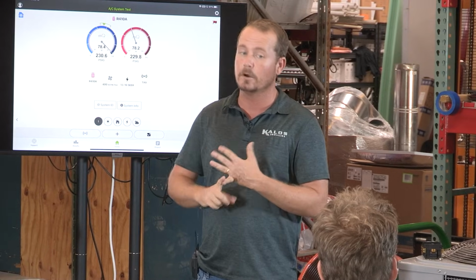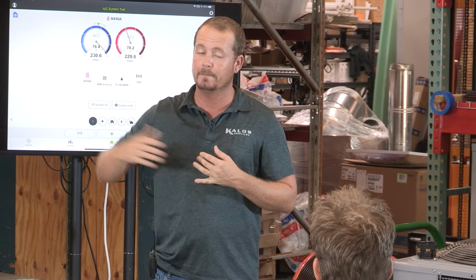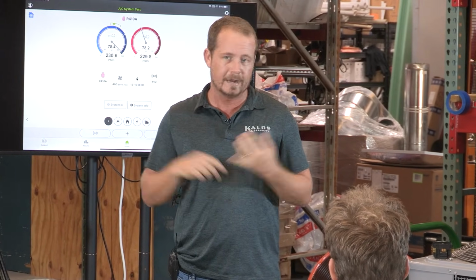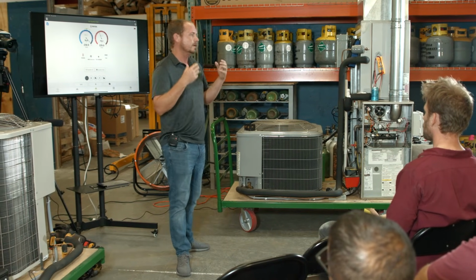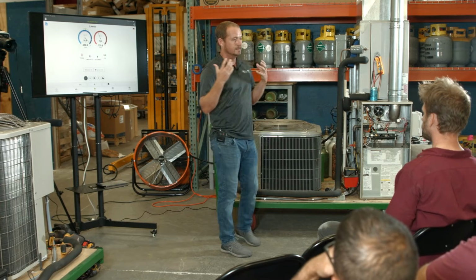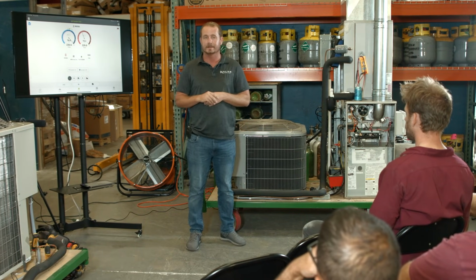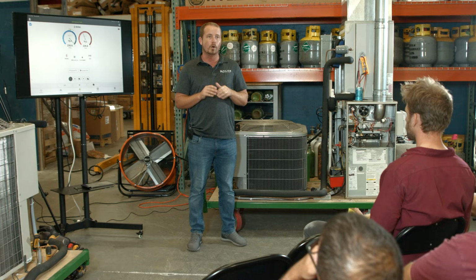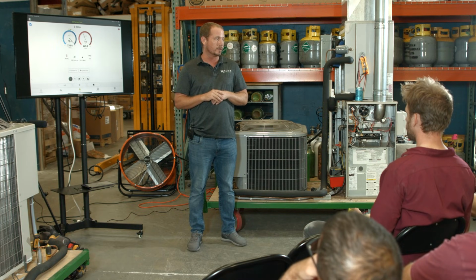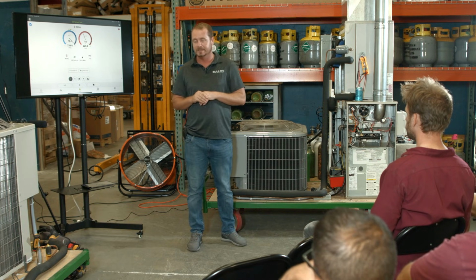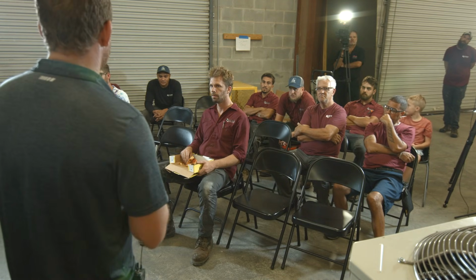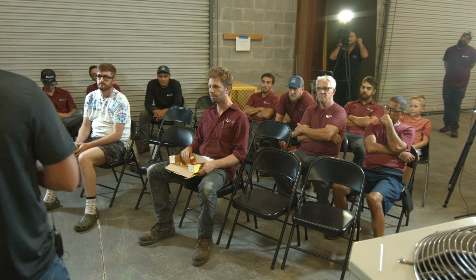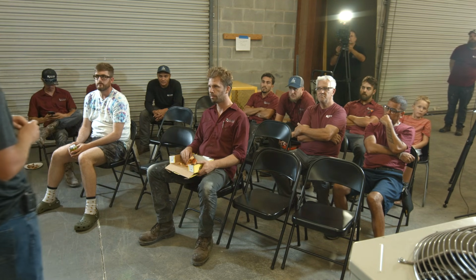All right, so with an ECM motor, if you hear it doing what Matthew was describing, where you hear a lot of air sucking in the cabinet or it's making a loud whining noise or whatever, then you suspect static pressure. You suspect that your static pressure is high. And why does that motor do that when the static pressure is high? Why does the air get noisy and the motor start to maybe vibrate a little bit more, make more noise? Why is that?